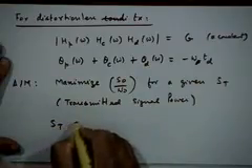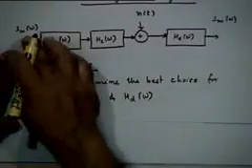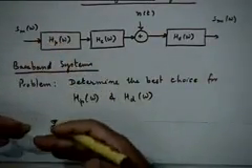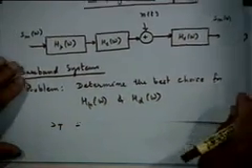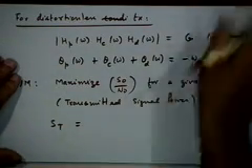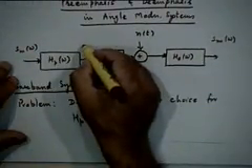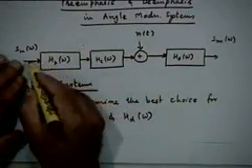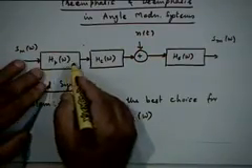Can you express S_t in terms of S_m(omega)? S_m(omega) is the power spectrum of the message signal. It will be the area under the power spectrum of the message signal. So S_t, sorry, the transmitted signal is not this. This is the transmitted signal. You are modifying the spectrum of the message through the pre-emphasis filter.